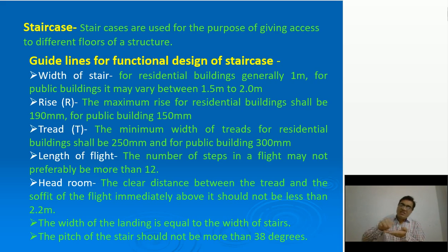Rise, that means the vertical height of each step. Maximum rise for residential building shall be 190 mm. Normally the range is 150 to 175, but we can extend it up to 190 mm. And for public buildings it is 150 mm.